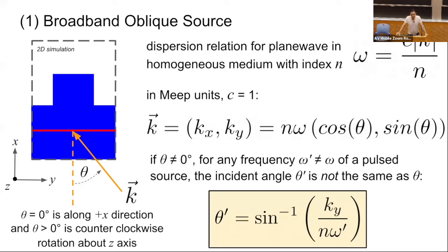So in my investigations, what I've noticed is that when you're coming in at off-normal incidence, there seems to be more error in the reflected orders than in the transmitted orders. When you're doing this test to validate the tally against the total Poynting flux, I needed to go to these large resolutions to be able to reduce that error, particularly for the off-normal angle for the reflected orders.